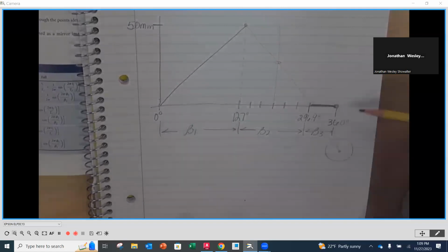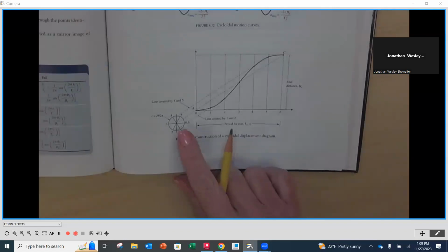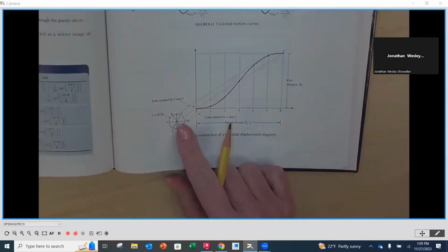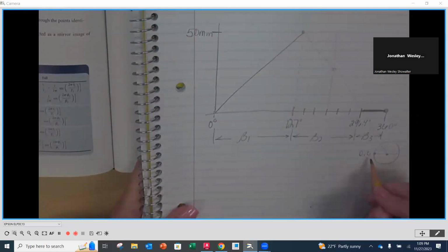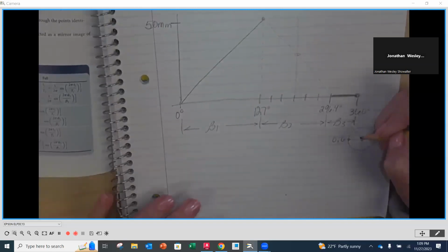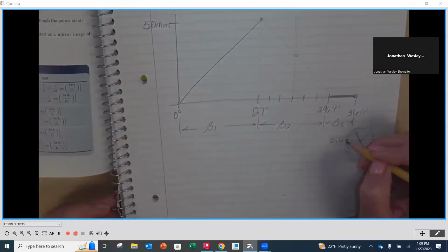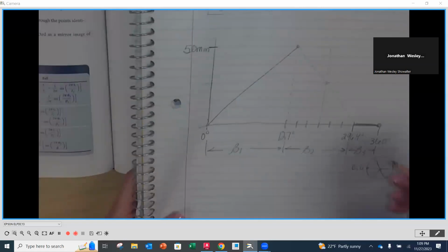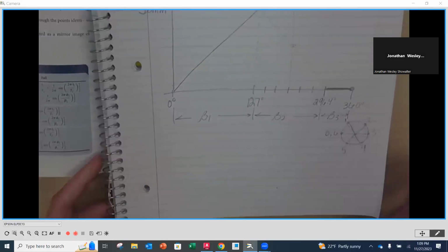Yeah. So now you'll do your cycloidal, and then you're going to create the construction as we see here. Okay. So we'll do our 0 and 6. You're going to have this evenly distributed into 6 sections in 30s all the way around. So 1 is going to be here. We have to go in the opposite direction. 2, 3, 4, and 5.